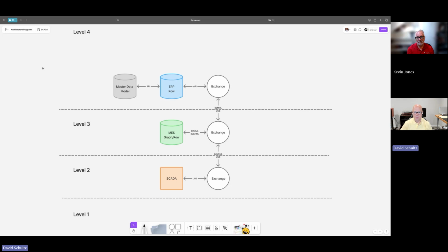Yeah, so within that exchange, there's also going to be schema validation to ensure that the data payload being exchanged has been properly formed. We're also going to do data validation, meaning that the information presented in that payload is correct and proper. A good example of that is if my ERP says I need you to make a particular material definition, material ID, or product code as it's generically referred to, I'm going to validate: does this product code actually exist in my MES? Do I know what this is? And if I don't, then it's going to reject the information and give you some sort of error handling response. And then, of course, with data validation and schema validation, you're going to now have the acknowledgement.